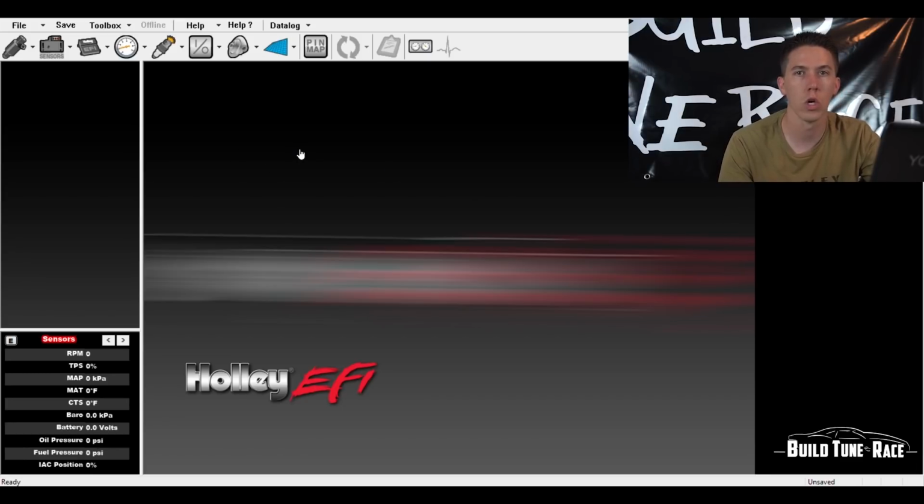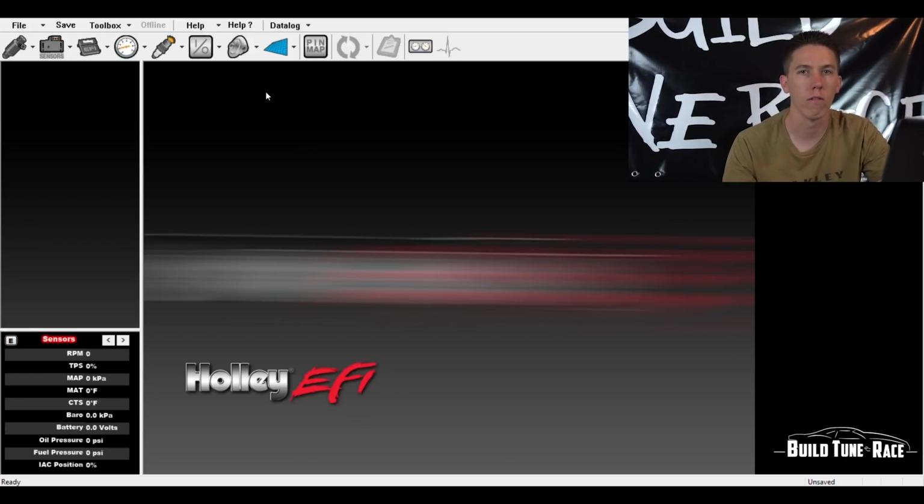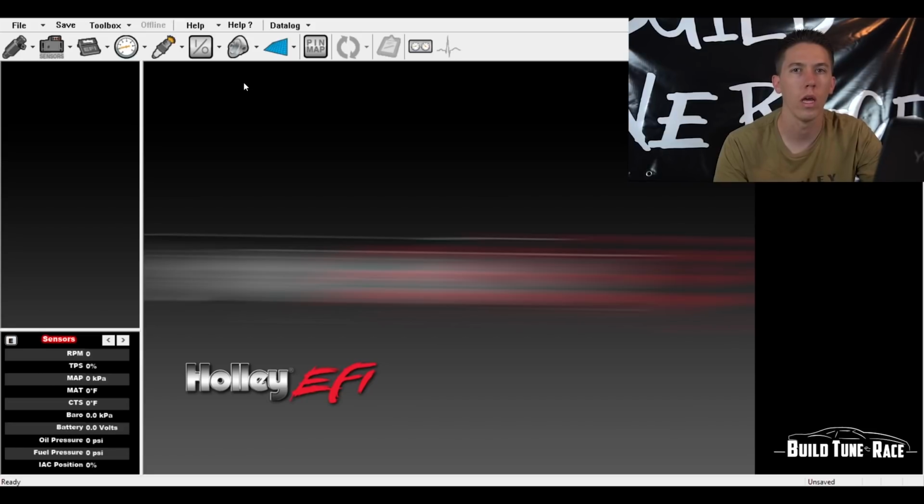This is dome pressure. So on the boost controller, it learns the dome pressure by a Holley 100 PSI switch. So I tell it it's a dome pressure. I wired it up the way that it asked, and then I dropped it down. This one works for the type of sensor that it is, and you just kind of read through it. I've set everything up pretty much the way the Holley says to set it up and where to wire it to. So you can drag these out, drop them, drag them back, drop them. This tells you that it can be different kinds of 5 volt, a ground, and different types of settings there.